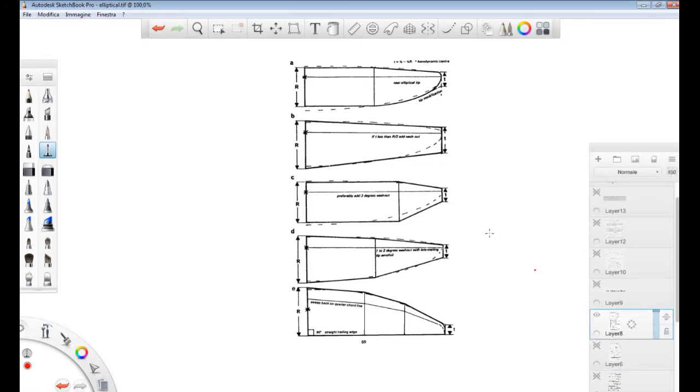As you can see, one of the main disadvantages of elliptical wing is construction. So in the past years, studies show that it is more important to have an elliptical load distribution rather than an elliptical wing form. So there are some approximations, as you can see, and this technique and also this one is valid to calculate the aspect ratio of a pure elliptical wing, which is shown here, because in an elliptical wing it is very hard to determine the tip chord and the root chord. So this technique is very useful.